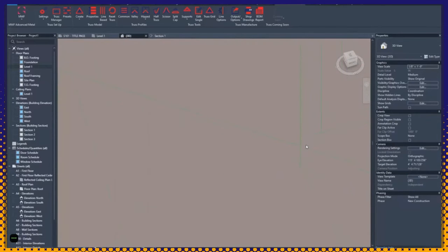So I was talking about the detailing tolerance and the setbacks tolerance. So the detailing tolerance is from the edge of this point to that line or the connecting truss there. Okay, so whatever member is being placed here, that's that tolerance that you're adding there. And then the setback tolerance is from that edge to this heel offset or this heel line. And that basically is identifying your member that's being placed for this truss.